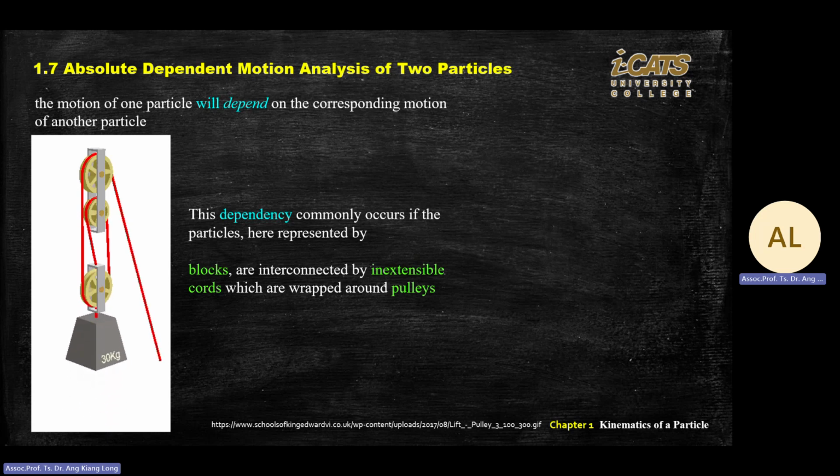It is always opposite to the motion. So you draw the arrow opposite the motion and write F sub f to represent friction, equal to the friction coefficient, and since you are in dynamics, you use kinetic friction, times N.